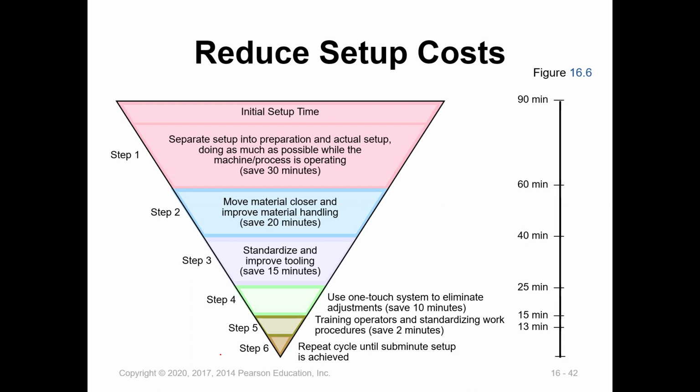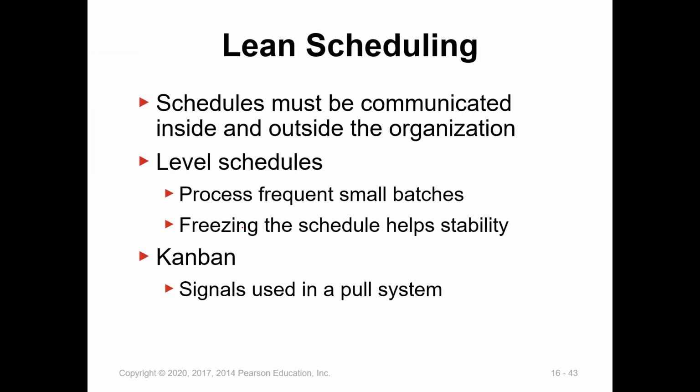Here, we separate the setup into preparation and actual setup, doing as much as possible beforehand. Every situation has a different solution. Move material closer and improve material handling. This will introduce standardized and improved tooling, as we mentioned in 5S. These techniques can be used to reduce the setup time, but for some situations, you need to do a separate study to reduce the setup time, like the example I gave.